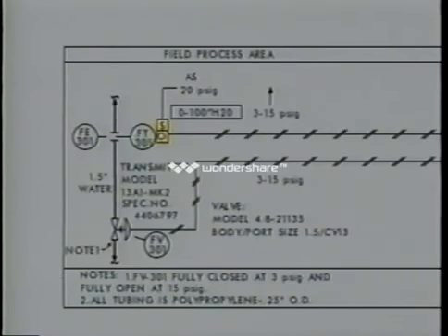At the transmitter, there are 2 connection ports labeled S and O. So the transmitter has a supply port and an output port. This transmitter has an air supply of 20 psig. A note here by the transmitter indicates that the output signal is 3 to 15 psig.